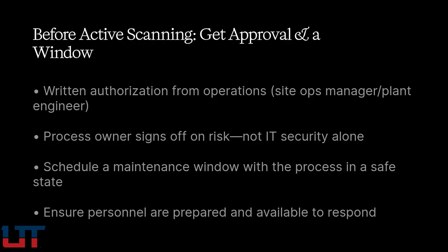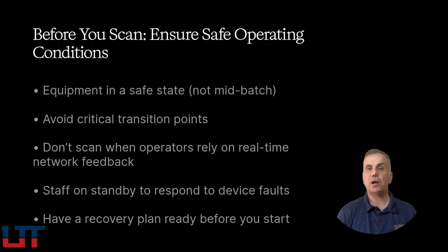A maintenance window where the affected process is in a safe state and personnel are prepared. The relevant field equipment should be in a safe operating condition, not in the middle of a batch, not at a critical transition point, not with operators relying on the network for real-time control feedback. Personnel should be stationed to respond immediately if devices fault.